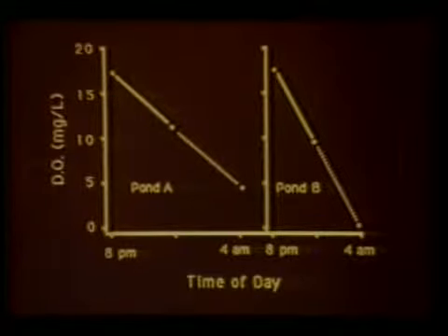However, the predictive models are not always foolproof. Therefore, they should be used with caution. For example, if after using the model your pond resembles the situation in Pond A, it may be wise to measure the concentration at dawn periodically to be safe. If oxygen levels decline low enough, corrective measures are warranted.